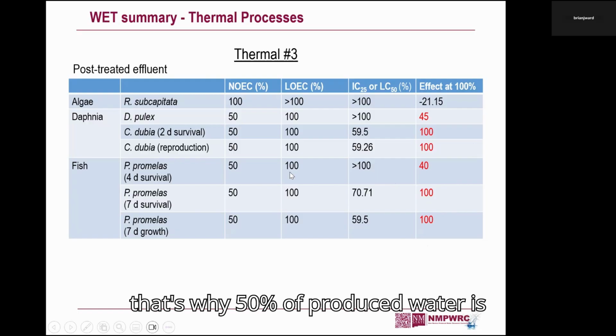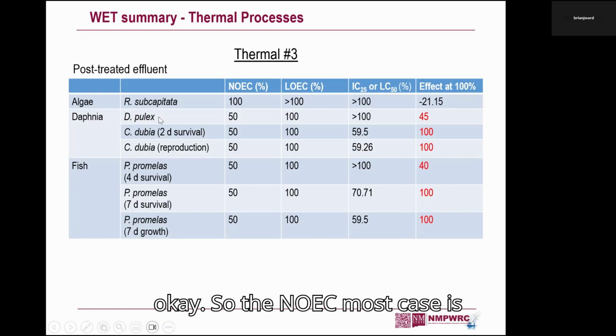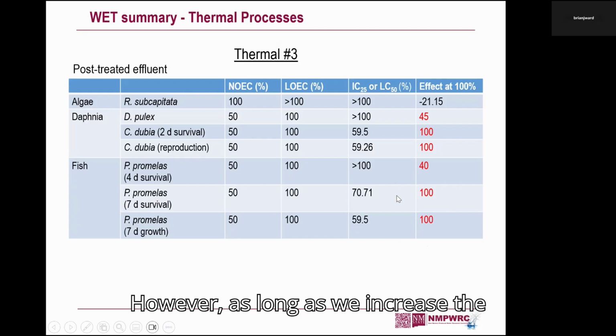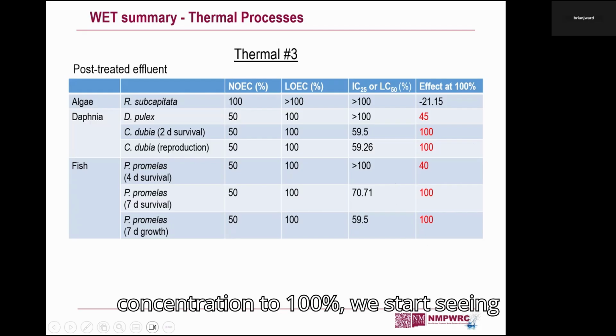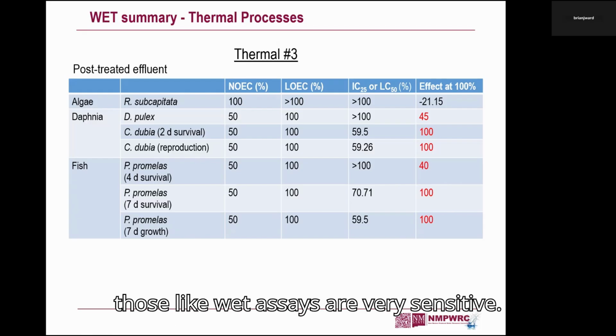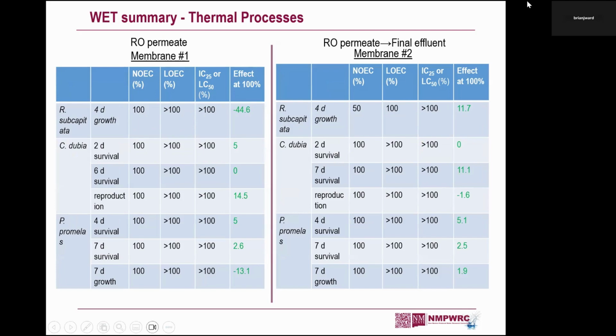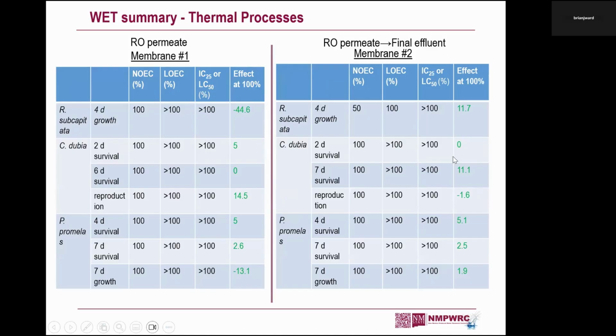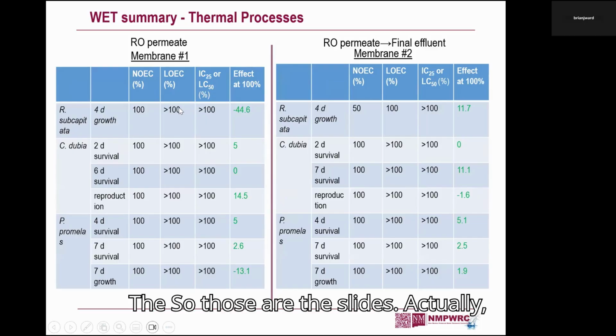So that's why 50% produced water is okay. The NOEC in most cases is 50%, so no observed effect. However, as we increase the concentration to 100%, we start seeing the problem. So as you can see, those WET assays are very sensitive. So those are the slides.